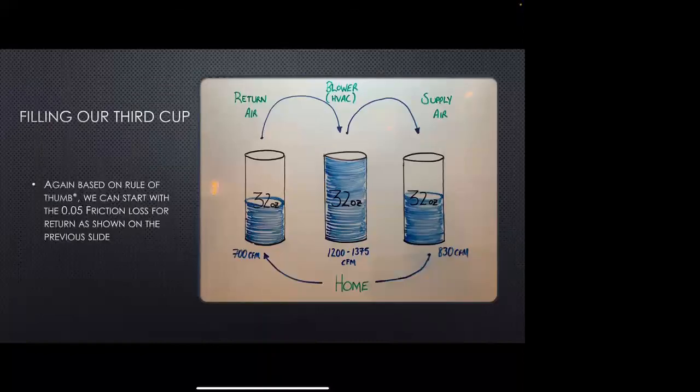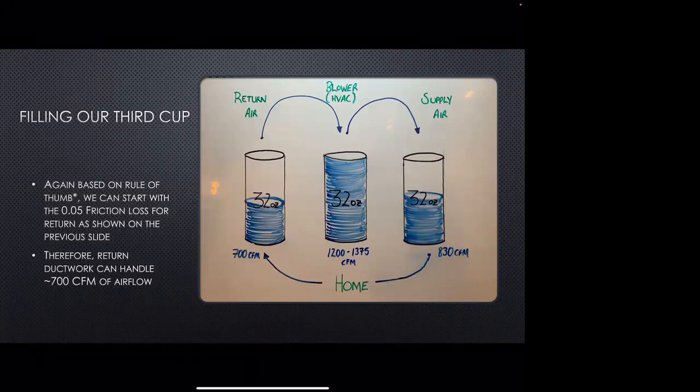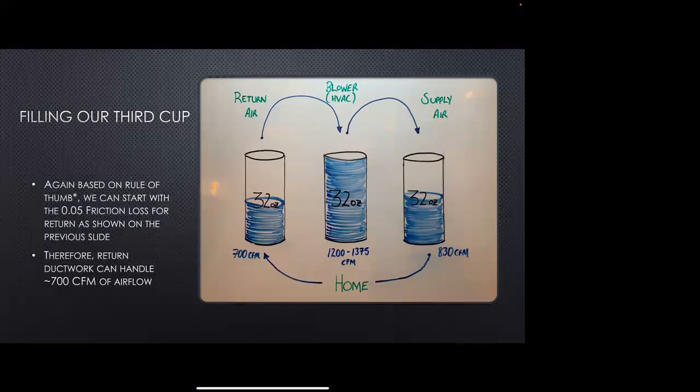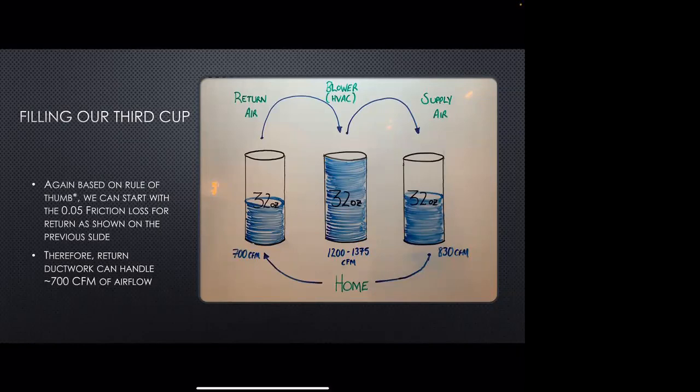the 3-cup analogy. Right? So if we can get the sizes of the duct that's immediately connecting to it, especially if the blower motor is out and we're setting up a comfort consultant to come out to do a like-for-like replacement quote, if we at least do something like this, that's very visible and easy for the homeowner to understand. And if it's easy for the homeowner to understand, it should be easy for our comfort consultant to understand that, hey, our cup's short. We're not giving the unit enough air. We're not giving this other cup here in the middle enough water. We need to address it.